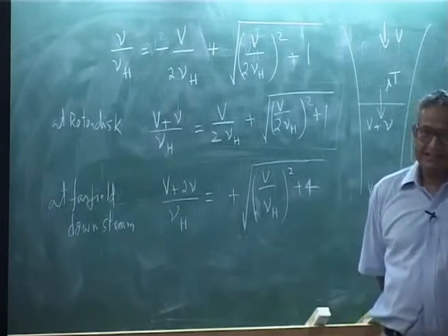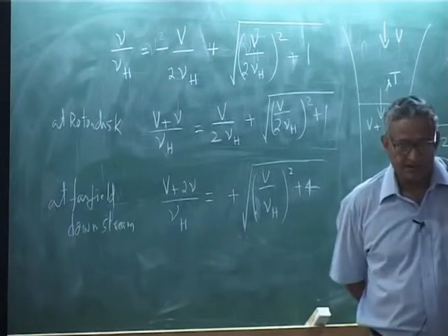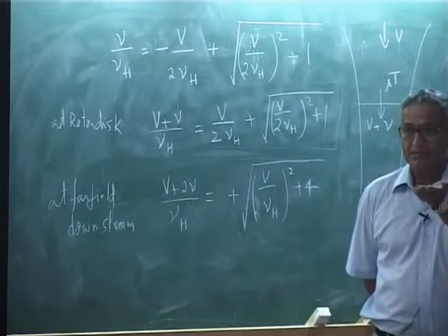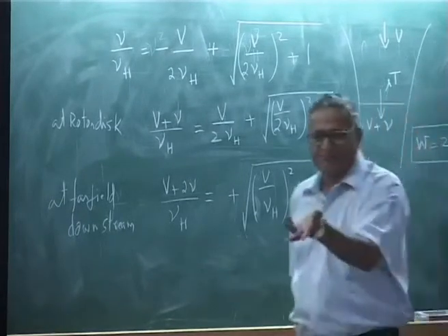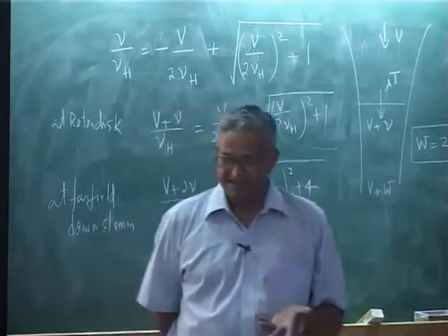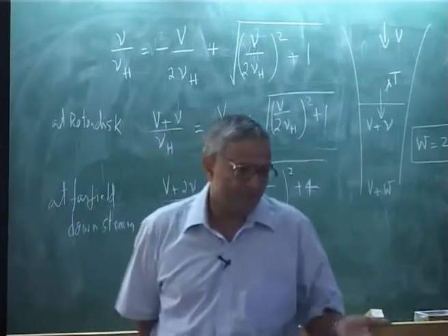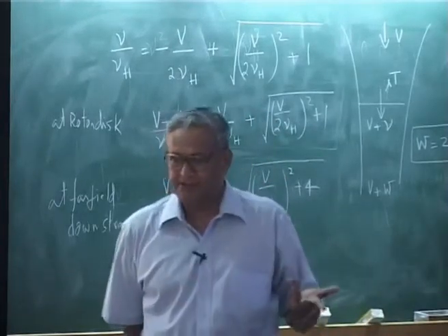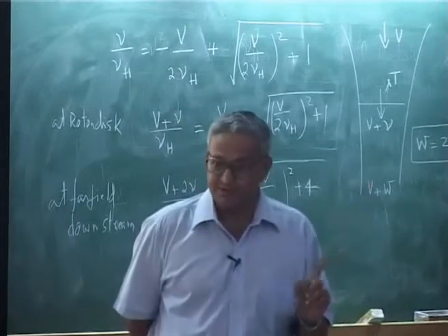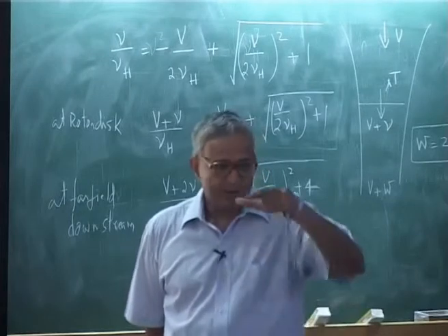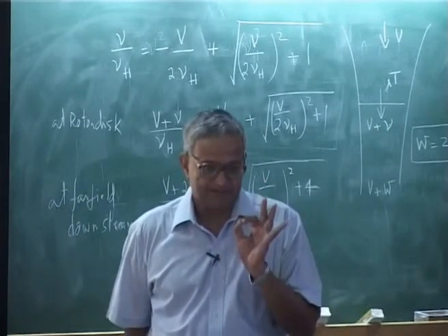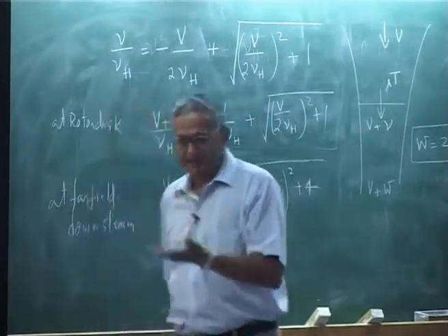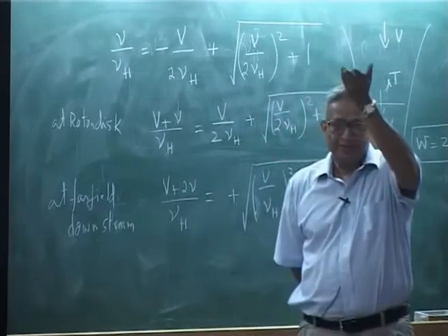So, you will find that the inflow through the rotor disc reduces when you are climbing, because basically you know that the mass flow rate you have increased. Okay? You increase the mass flow rate, I have to support the same weight. Since I have increased my mass flow rate, my velocity can be less, that is all, induced flow, and this same concept will come in forward flight also. So, you will find your inflow means nu, please understand, that value keeps decreasing as you increase your climb velocity.